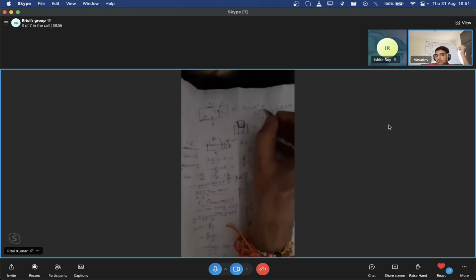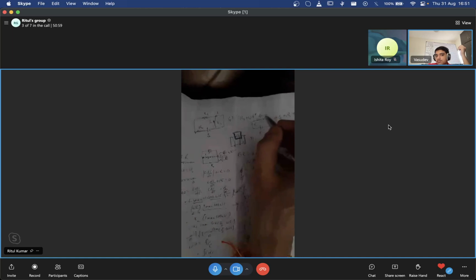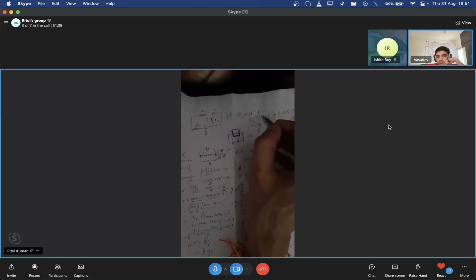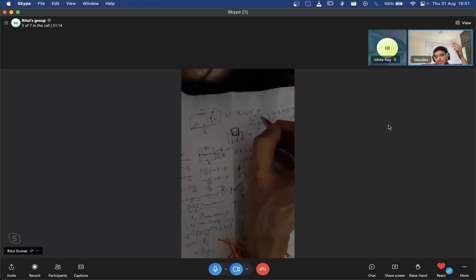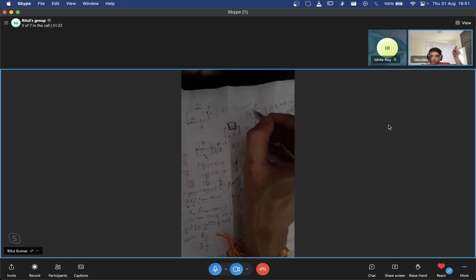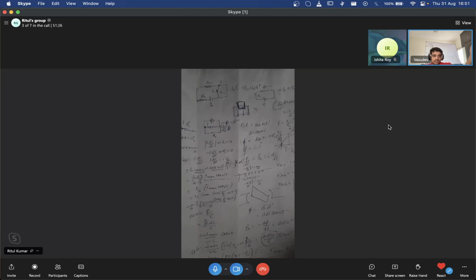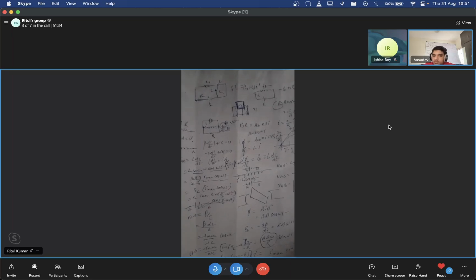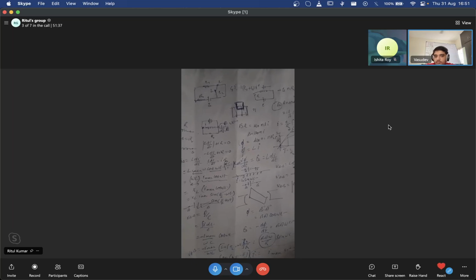That was current. In this case, also current was clockwise there, but it behaved this way, right? Because it depends on what is happening. It is not on the flow of current; it's on the rate of change of flow, right? Mm-hmm. So it depends on the rate of change of flow. I'm not deciding on flow of current. Resistance is different from inductor. Yes, sir. So all I'm saying is the potential across the resistance is independent of how the current is changing. So that'll always drop. But if it also drops in the same direction across the inductor, then that lost potential cannot be made up. So if you go around in a loop, sigma V won't be zero, right? Correct. So I'm saying option A isn't a potential choice.